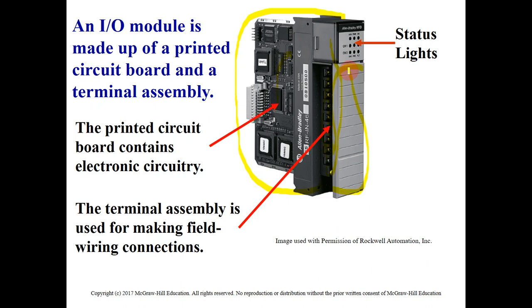It will just be removed, then it can be plugged into the PLC system to run it or to make it in service. Here we have the status lights, and as we mentioned before, the status light here is a good indicator to show you which sensor is in service. So for example, it will be a green light. If a sensor has a problem, for example, it will have a red light. So this LED is actually used to show you or indicate the status of the real circuit in the field.